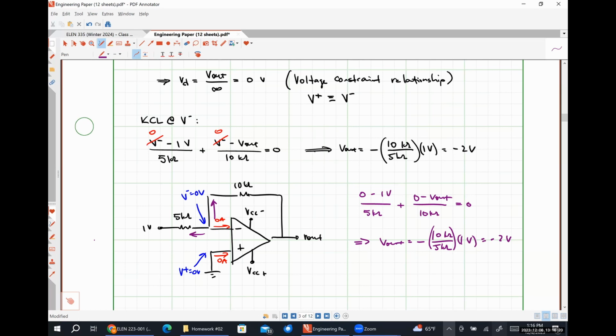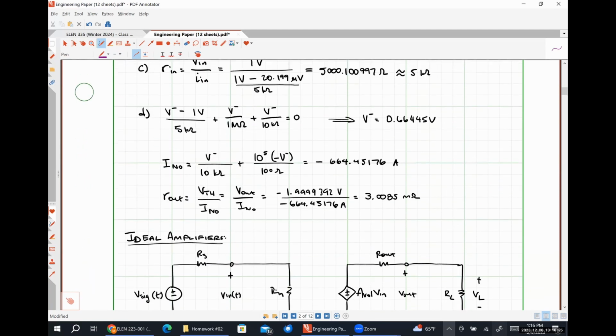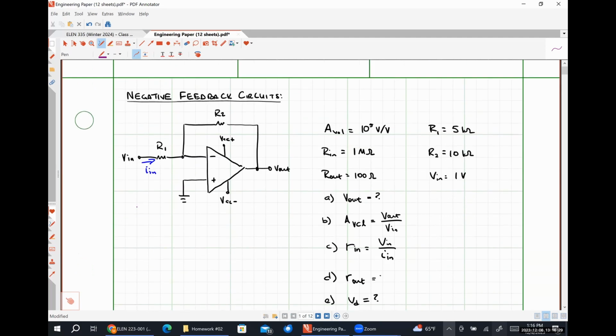So in your homework, I'm going to ask you guys to go through these steps and all of that kind of stuff with another situation like this, where our input signal is applied at the inverting input through a resistor network. I'm also going to have you do one where we apply an input voltage here, and you'll see that the output resistance is effectively always going to be something incredibly small because it needs to be as close to zero as possible to make sense.